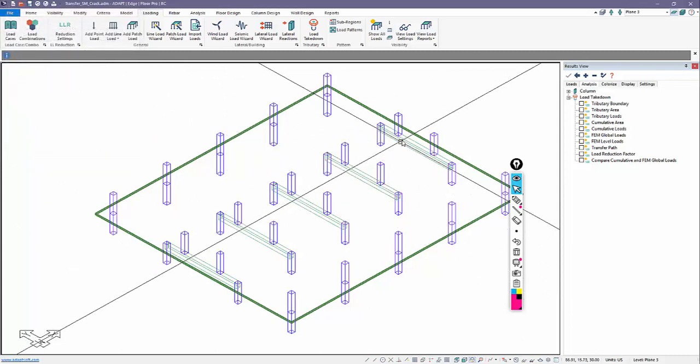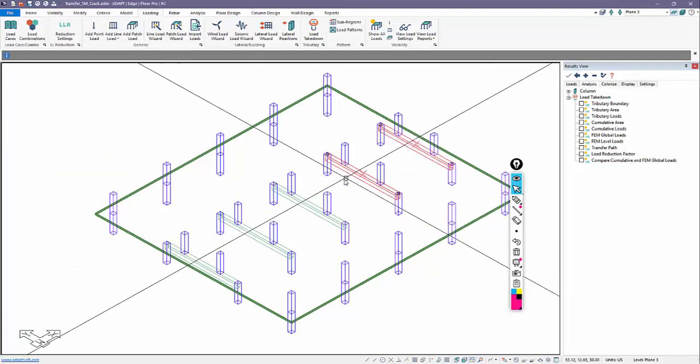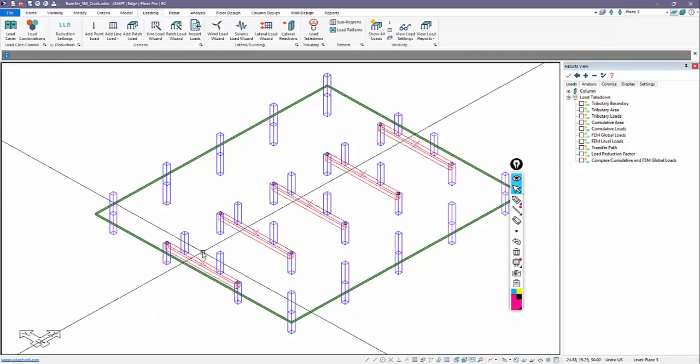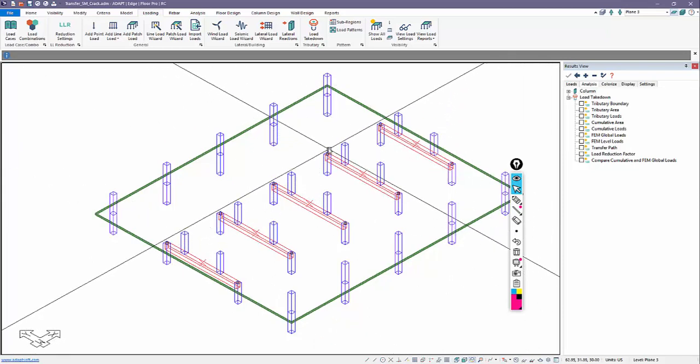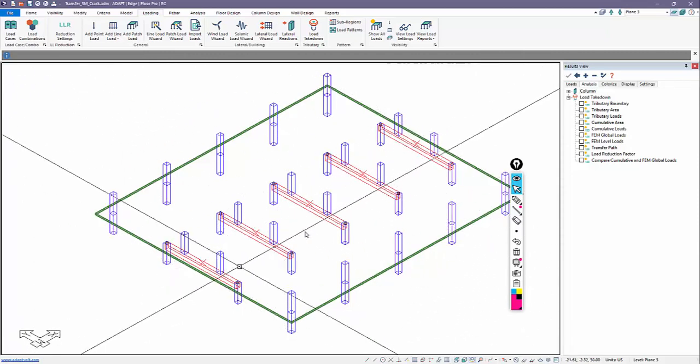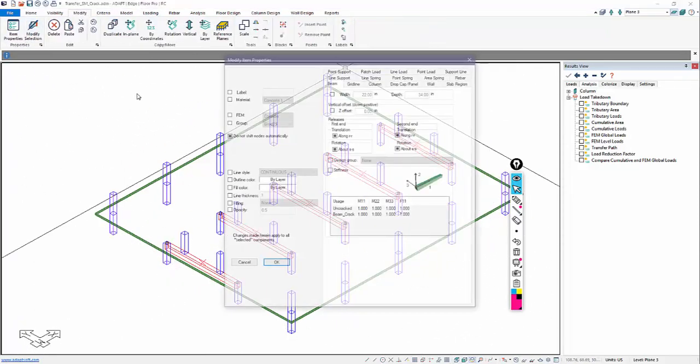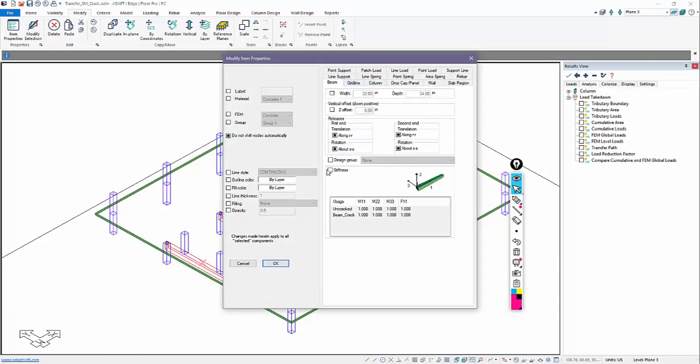Okay, now I'm going to select these beams. And in this case, we don't know to what extent the beams have actually cracked. We're just applying a modifier that is approximate. Maybe the ACI code or another code says for second order effects, for strength, for this, for that, we apply certain modifiers. So we'll apply a modifier of 0.35 to this beam for flexure, just as the example. After I set up the usage case, I'll select the beams, I'll use modify selection, and for beam we're going to go to stiffness and we're going to change this to 0.35.